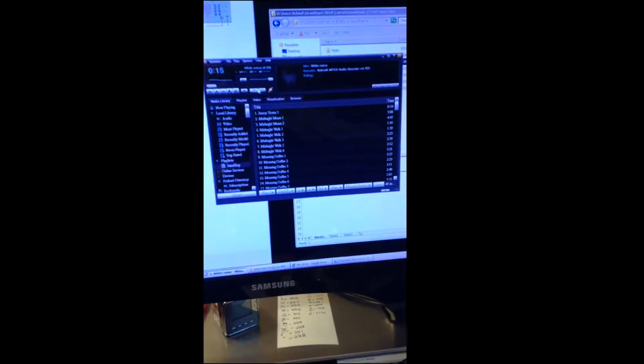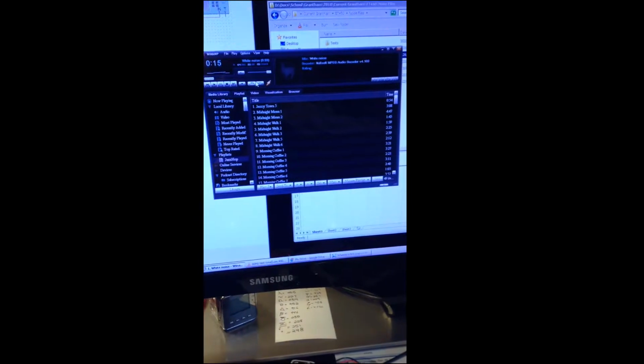So how we're going to be testing here is that I have a white noise 10-minute audio file that I'll pass through the system, and it'll go through the circuit card. We're going to do it in bypass, and then apply the high pass filter and then the low pass filter, so that you can see on the spectrum analyzer the difference in how it applies.